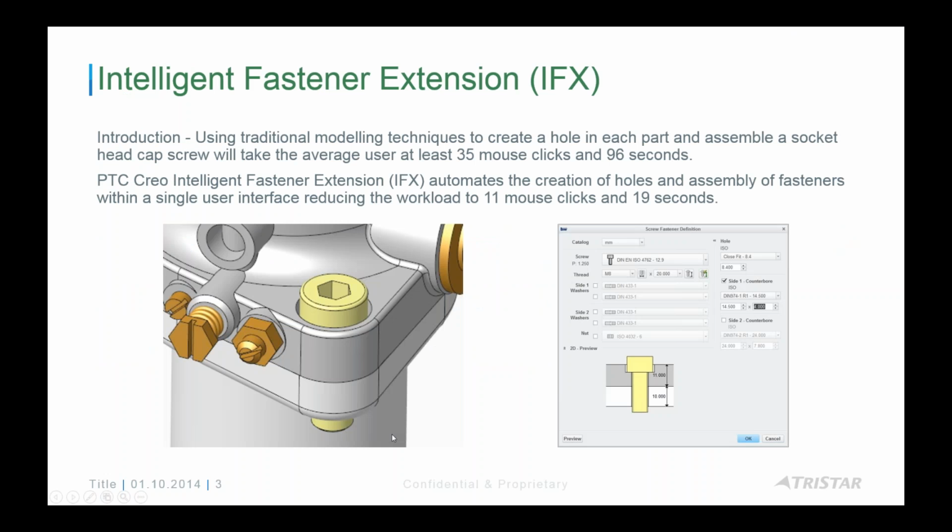So the Intelligent Fastener extension, IFX, allows us to quickly assemble fasteners and create holes in our parts or models. Using traditional modeling techniques to create a hole in each part and assemble a socket head cap screw will take the average user at least 35 mouse clicks and approximately 96 seconds.